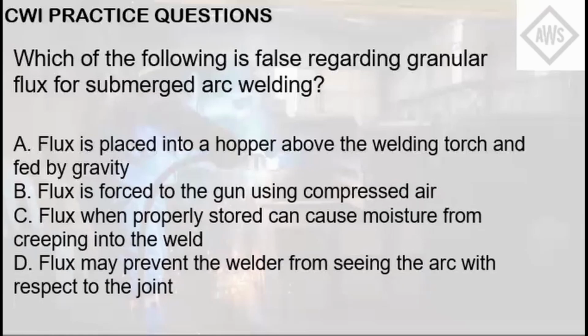One thing you can remember, or one safety precaution that you may bypass in SAW, is that you may not use a welding helmet, you can just use goggles, because the granular flux might go through your eyes. The normal welding helmet is to prevent you from seeing the flash, but a flash in SAW is non-existent because the flux is covering the arc. So that's something to remember as well. So the answer here is letter C, or I'm sorry, the answer here is letter C, not D.